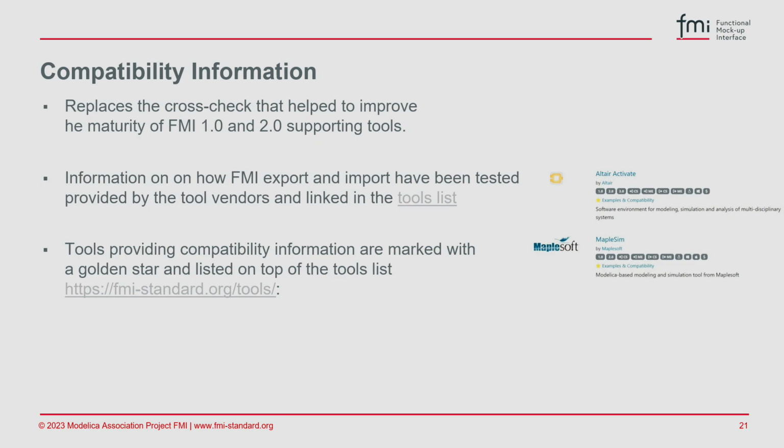This is natural. This means that they didn't talk to each other. But I mean not more like deep incompatibility. So if we have an FMU that is corrupted by its nature, regardless of how I try, because I may be fighting to make it compatible, but it could be a deeper issue behind this that I'm not aware of. So typical examples are in the XML. These are things that you can really validate and say this is right or this is wrong. What is more complicated is when you, for example, connect 10 FMUs and try to do a co-simulation and something goes wrong, then it can have lots of different reasons.